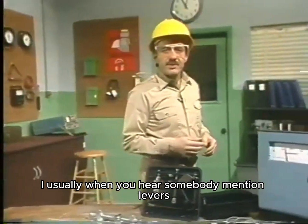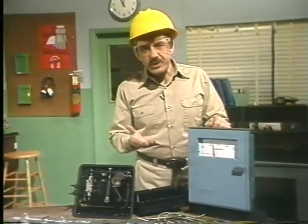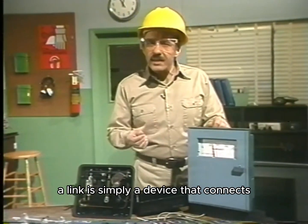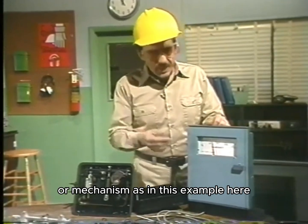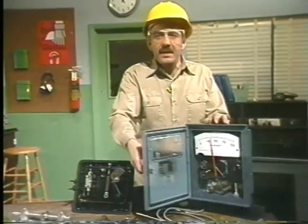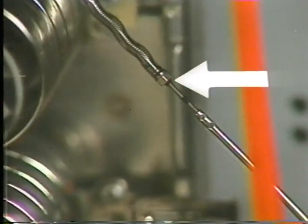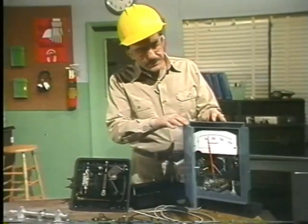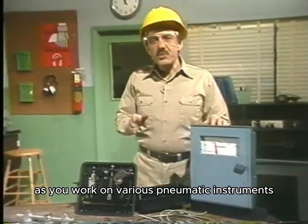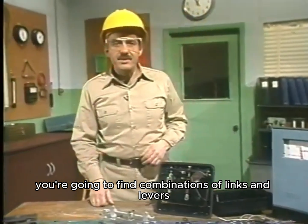Usually when you hear somebody mention levers in reference to pneumatic instruments, you'll also hear them mention links and levers. Now, a link is simply a device that connects a lever to another lever or mechanism, as in this example here. As you can see, the length of this link is adjustable. Often this adjustment is made when this instrument is being set up or calibrated. As you work on various pneumatic instruments, you're going to find combinations of links and levers different than the ones